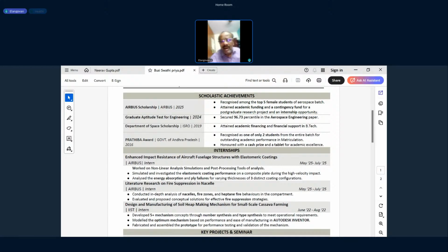We are going to DRDO. You should know weight, dimension, propellant, type of control system. What is the material used in the fabrication? What are the temperature ranges, pressure, velocity? What is dynamic pressure? When will the bending moment be maximum? When will the load be maximum? What is alpha max? What is Q max? What is Q alpha max? What is a thrust curve? All these things you must know because you are going, you must know about rockets.